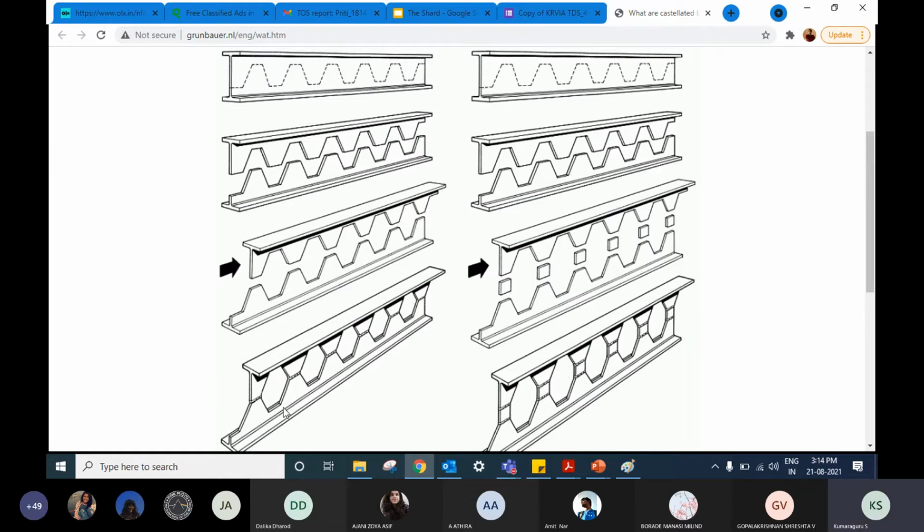Now, this kind of formation is called a castellated beam. Essentially, what happens is when you run out of beam depth, I think this became very famous during the World War times, like during the First World War and Second World War. They had massive production. There could be a certain amount of depth only that could be rolled in a mill, right? Like it's readily available in the market. So if they wanted to increase the cross-sectional depth, they did this. They cut this, welded it, and now you have an increased structural depth.